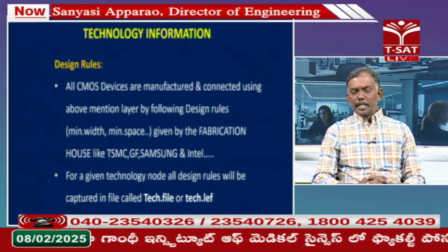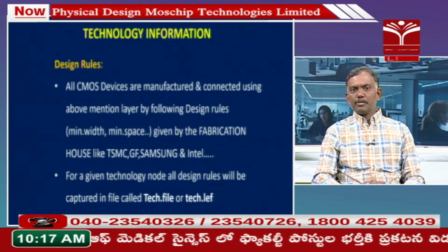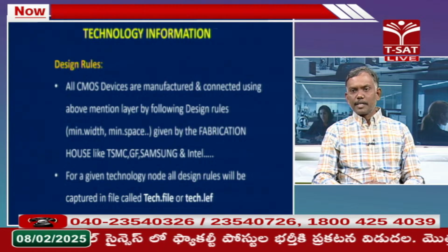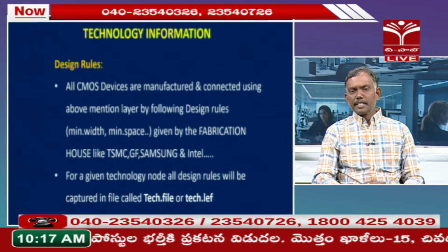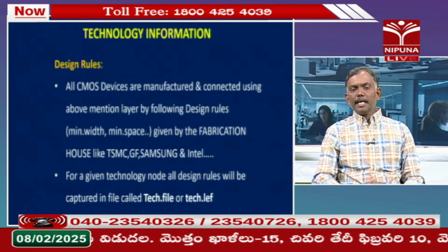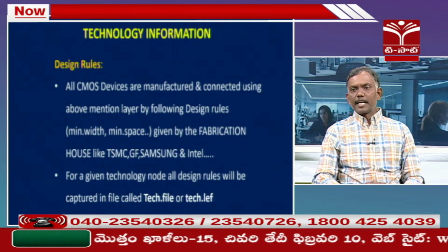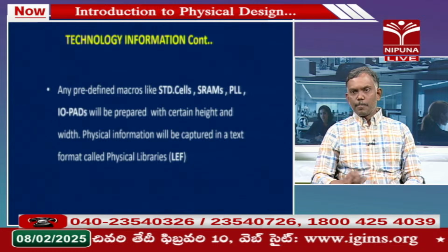Including these base layers and metal layers, we will create a file with all design rules, called the tech file, used by the analog team. And for the digital team, the base layers information is in general not required. So we will capture only metal related design rules in a file called techlef. That is one file which is useful in coming stages.